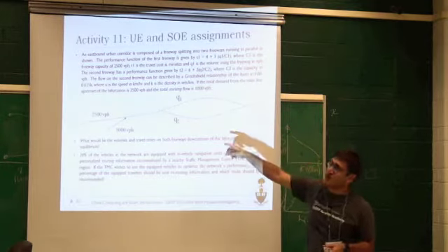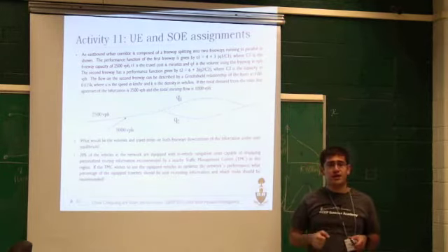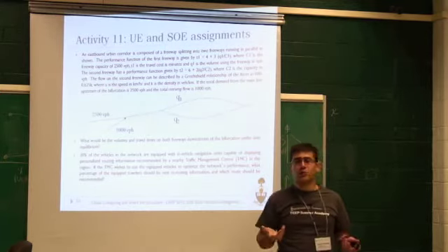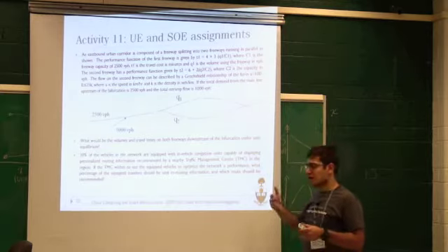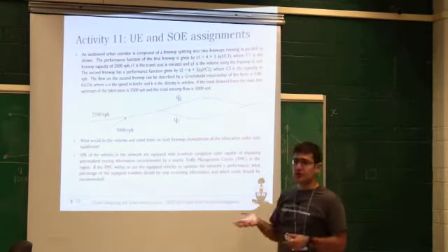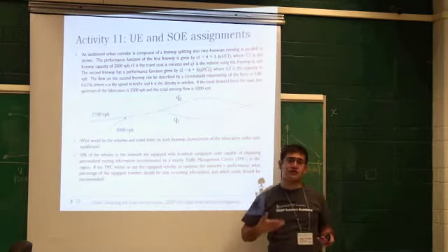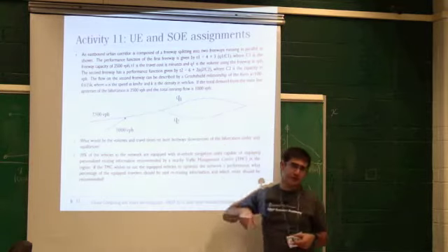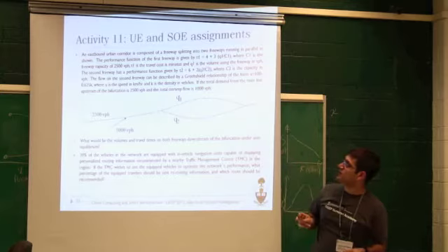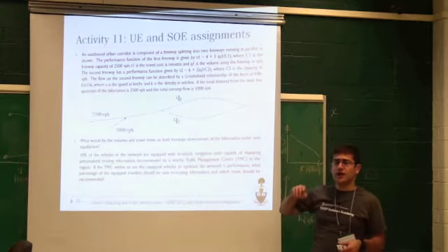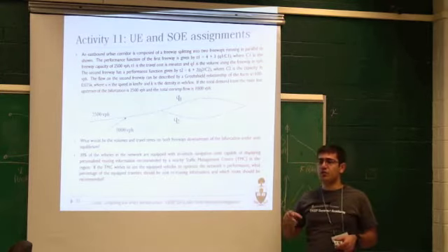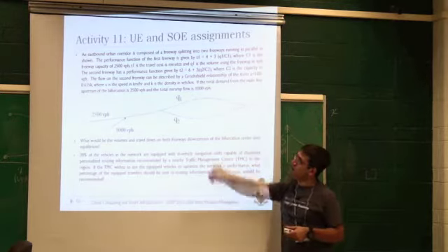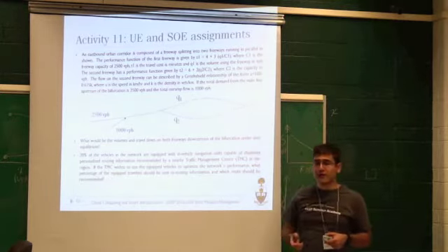And 0.625, which is the slope, it's a negative slope. It is how much my speed would be reduced due to the additional traffic that I have, additional density, which is K. So if you equate 0.625 to Vf over rho j, you have Vf being 100 and rho j, you'll be able to calculate it.